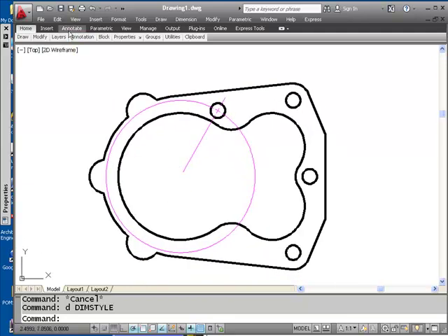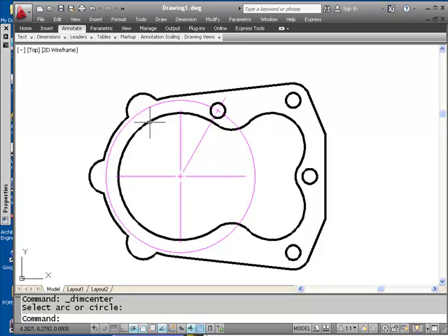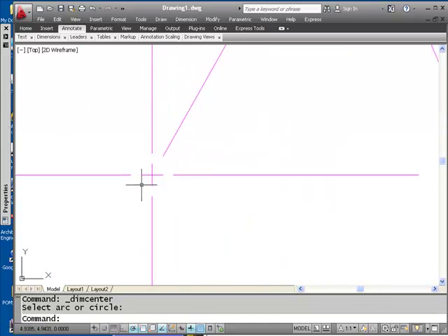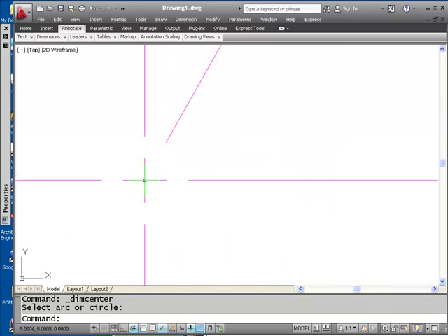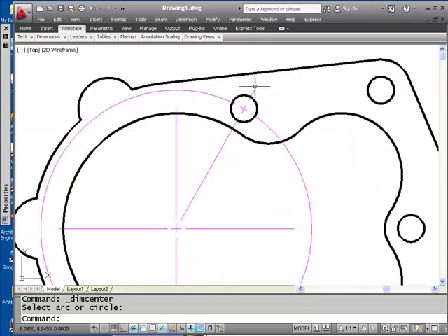I can get that under Annotate if I want. Under Annotate, I go over here to Dimensions, pick Center Mark, pick a center mark like that, and it gives me a crosshair. And that crosshair is now a 1/16 from here to here. The gap is a 1/16 from here to here, which means everything is consistent. Now what I need now is to take that repeatable pattern.